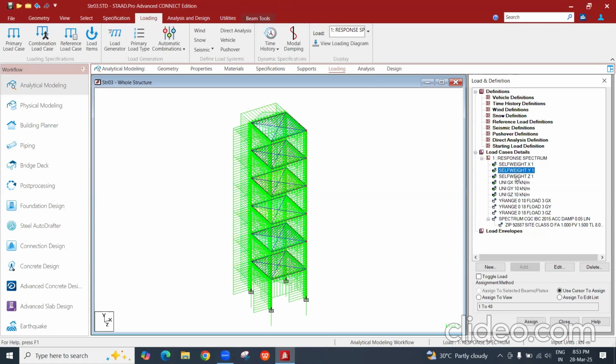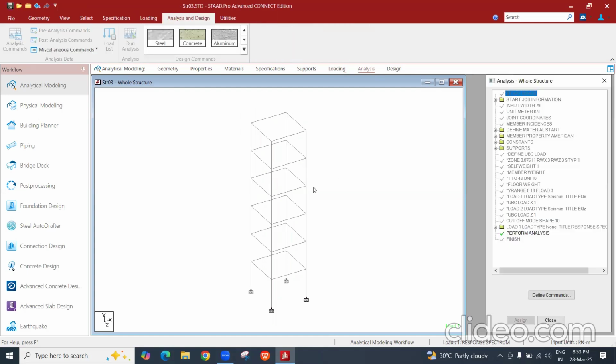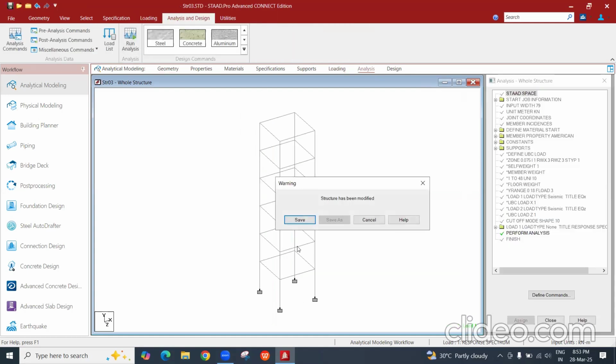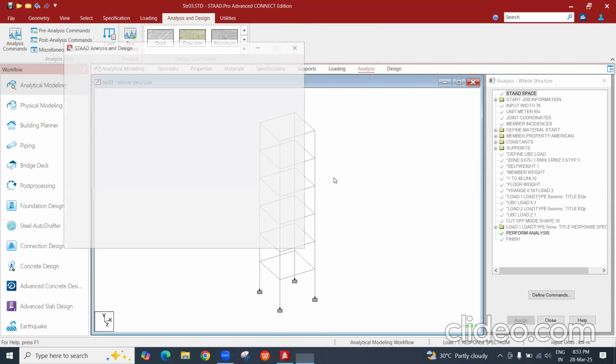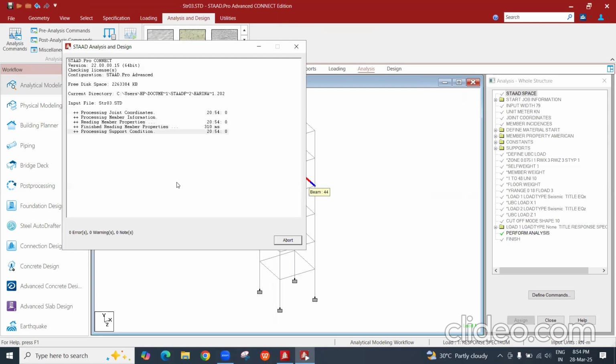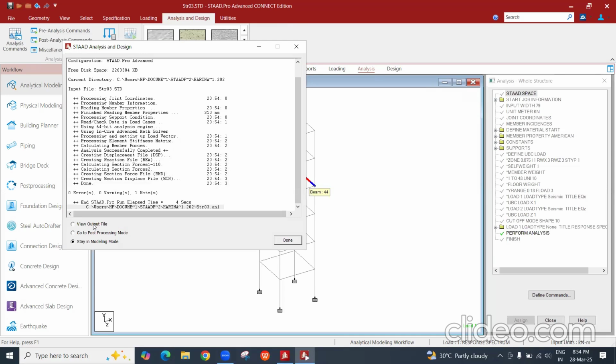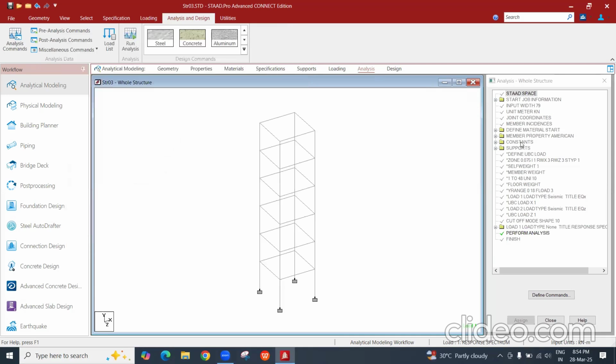The self height, in any direction, it will be one, correct? Yeah. Okay, I will delete this and I can put it again. Now we will see only with this what we are getting. Without any response spectra, if it is coming, then there is no issue with it. Zero error only we are getting. Okay, then maybe the problem is in the response spectra.